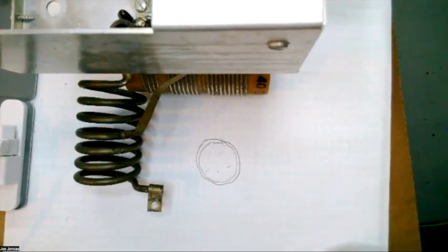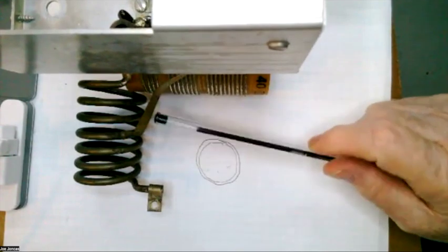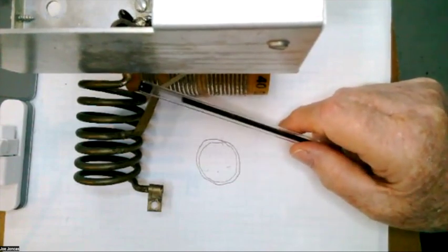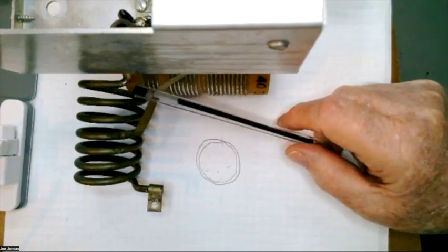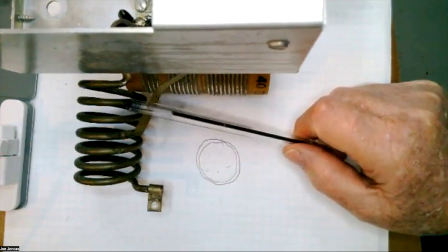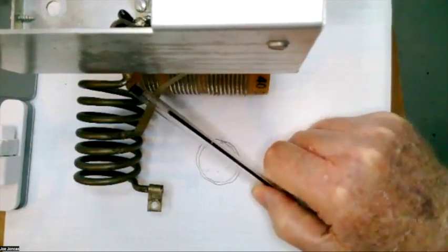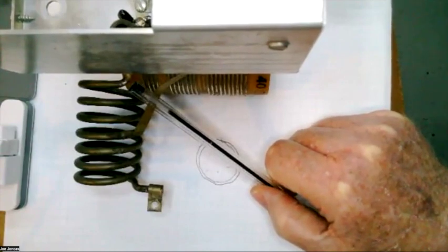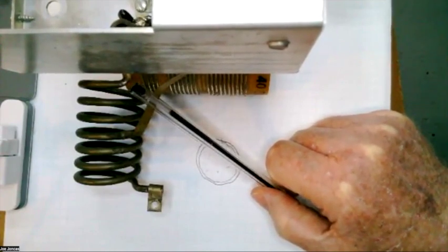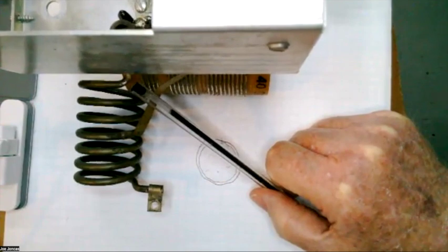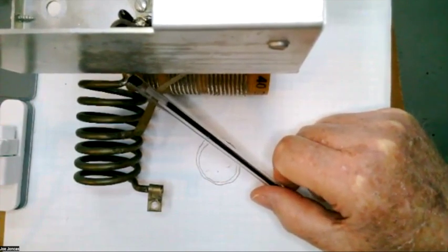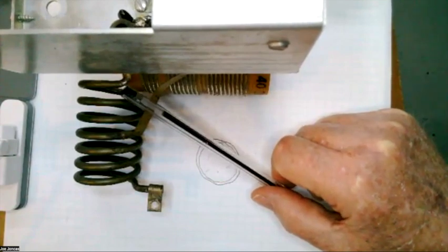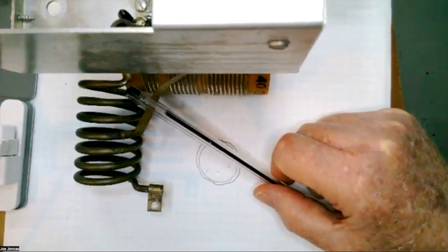We will later be studying what pi circuits are and how they work. Now, unfortunately, a pi circuit I cannot mathematically show you, but I can show you how it functions. It'll take the output impedance of a tube, which might be 2000 ohms, and turn it into 50 ohms.